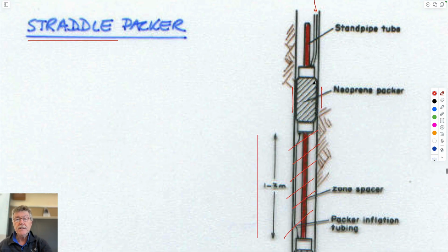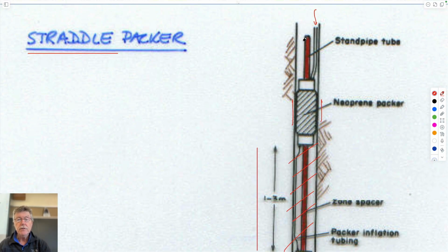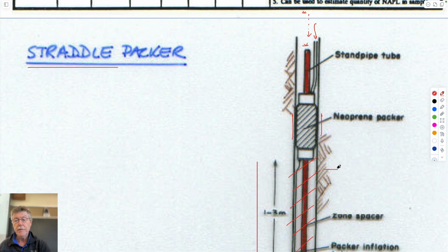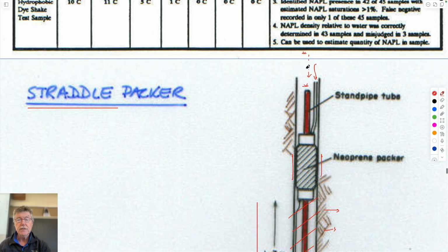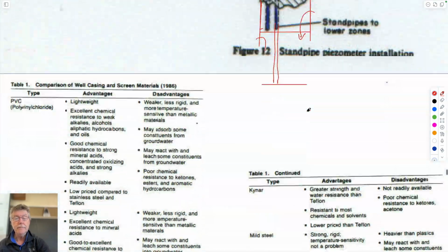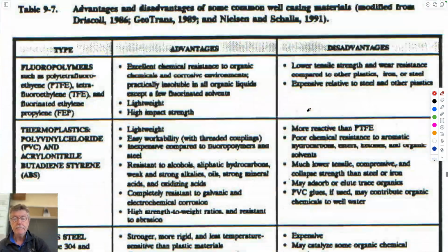So the red line is where you'd fill it up to some level within this line. You'd overfill it to some higher level, and then you'd let this flow out of this zone into the formation. In doing that, there's a complementary volume: every volume that goes out here comes down here, so you know exactly what this volumetric flow rate into the formation is, and so you can calculate permeability. When you've got the measurement, you deflate the packers, you winch it up the borehole to where you want to go, and then you inflate these again. It's a very standard way of doing that.